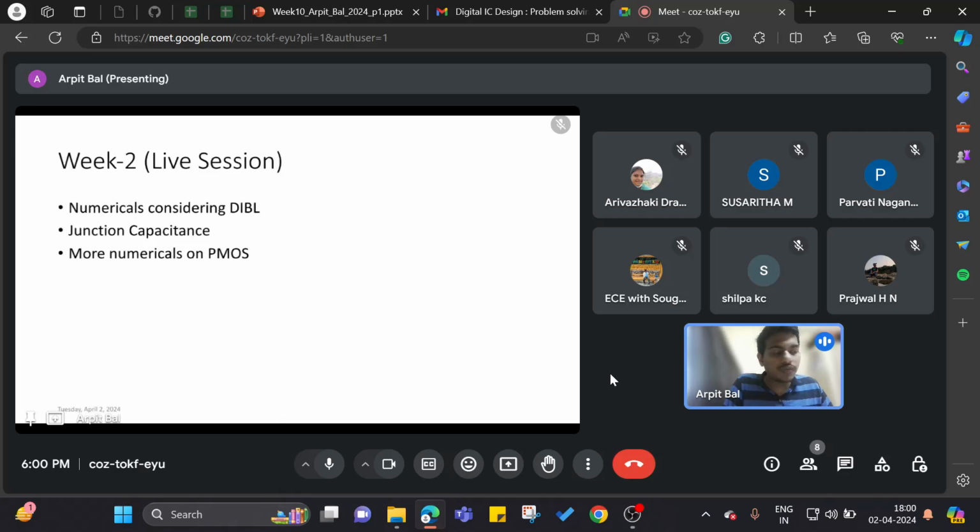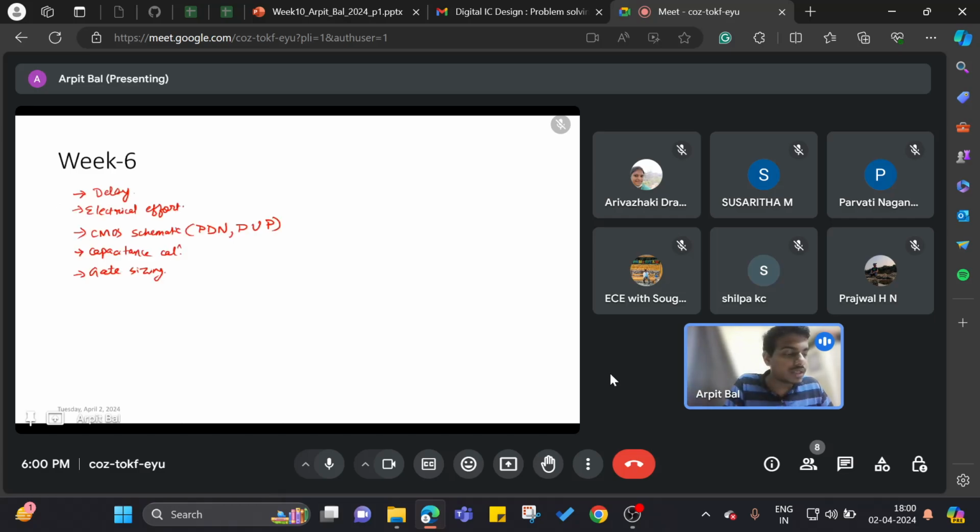Then in week 2, we did problems on DIBL, junction capacitance calculation, and PMOS transistor calculation. Week 3 was related to numericals based on VIH and VIL, and also the inverter trip point. Week 4 was related to noise margin and Elmore delay. In week 5, we did questions related to power, power delay, and process variation.